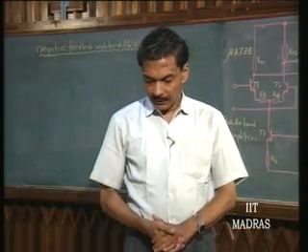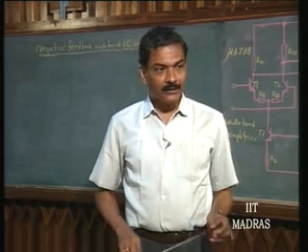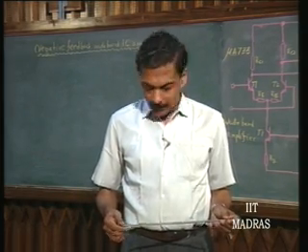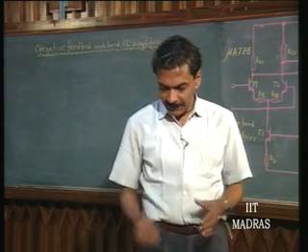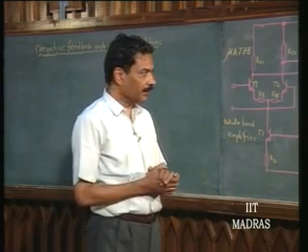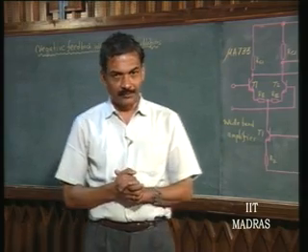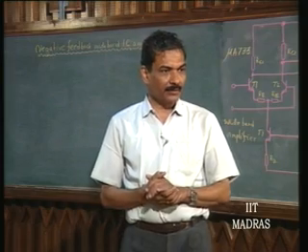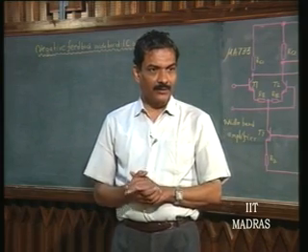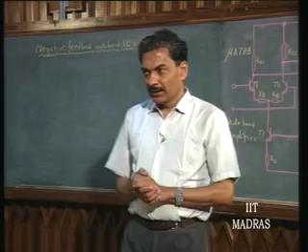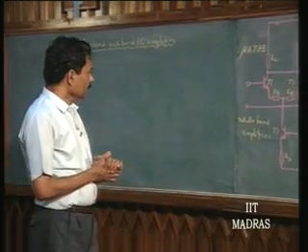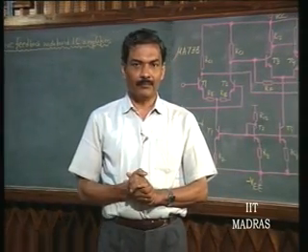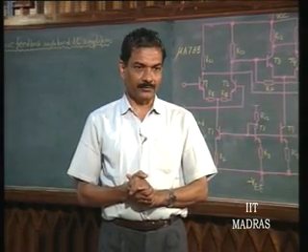Last class we discussed wideband amplifiers which used pairs without any feedback, and we came out with a very important configuration, that is the cascode configuration for the wideband. And we had other configurations like common collector cascaded to common base, common collector cascaded to common emitter, things like that. So, in this series of lectures we will discuss negative feedback and its use in widebanding.